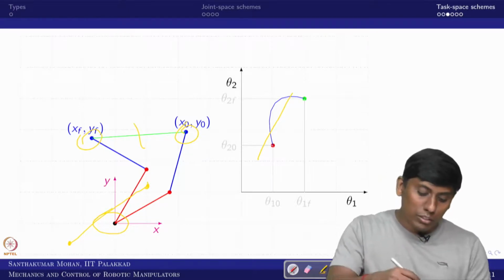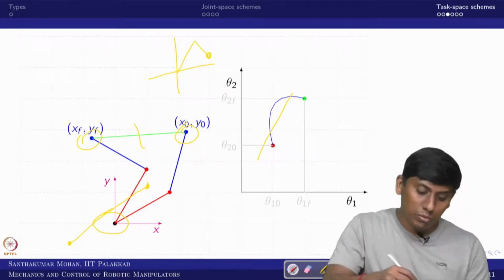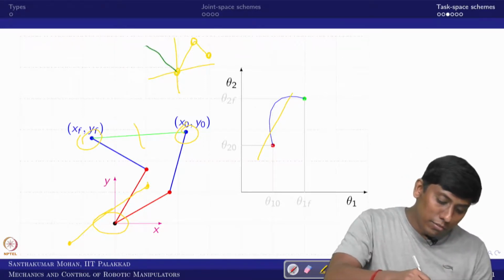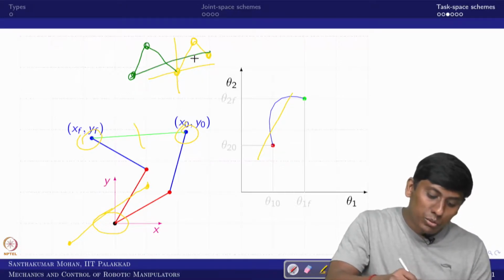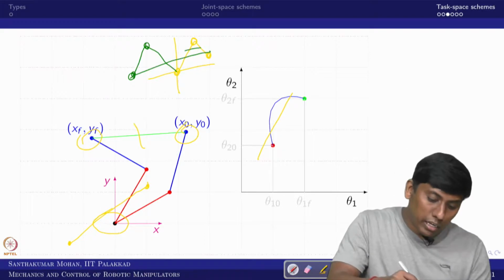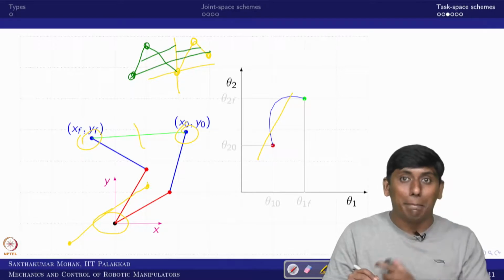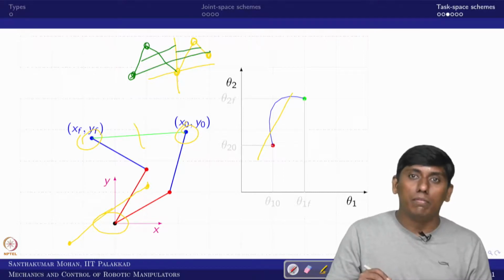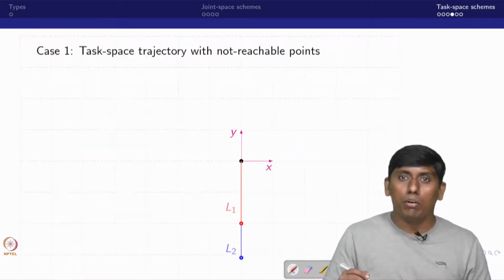In the sense, infinite joint torque is required to control that, which is not preferred. Similarly, the other way around, you have two situations that can happen. For example, this is one position of the manipulator and the other position is just a mirror image. If you are making it, it is supposed to come to the other path, so it goes like this and suddenly it has to come back. It is very difficult to follow that way. In that sense, the swapping may end up with discontinuous velocity and acceleration. All of these can happen. So that is what we are trying to see.